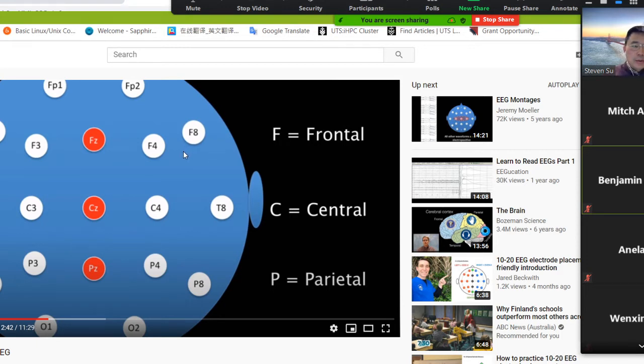To reject the disturbance, normally we need to use a differential amplifier with a very high CMRR, called common mode rejection ratio. So we need to reject the common part, and be sensitive only to the difference part.